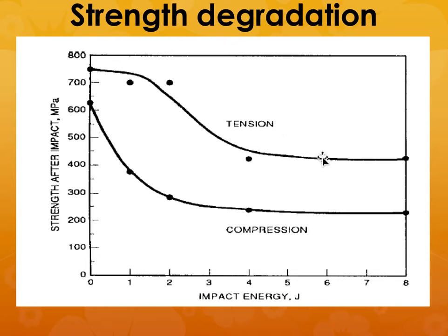Depending upon whether the impact creates delaminations or not, and whether the component is under tension or compression, and depending upon the impact energy, the properties can be lowered.